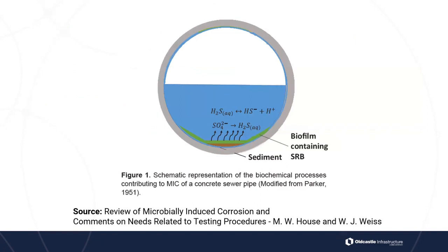All right, so the presence of dissolved sulfides in the waste stream is required for the formation of hydrogen sulfide, which is obviously a component necessary to initiate microbial induced corrosion in sewer networks. Remember, once our dissolved oxygen is less than 0.1 milligrams per liter, the reduction process can begin. At this point, we can design to decrease turbulence. Engineers can look at this and say, we want to change the flow of the pipe to make sure it's a laminar flow and not turbulent.